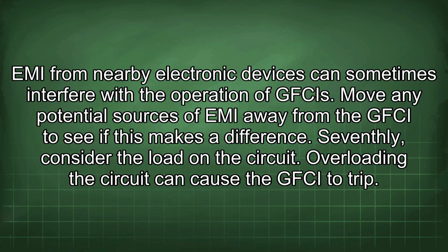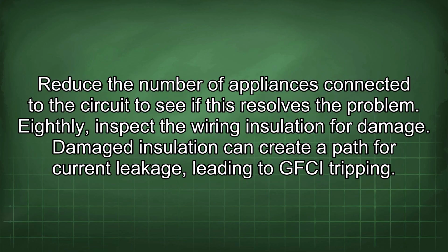Seventhly, consider the load in the circuit. Overloading the circuit can cause the GFCI to trip. Reduce the number of appliances connected to the circuit to see if this resolves the problem.